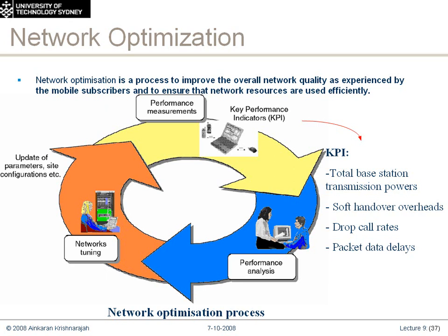So if you can think about moving the angle of the antenna backwards, so to speak, then the radio signal sort of goes up in the air a little bit more, and then hence covers the black spot a little bit better. But at the same time, what it does is it puts a down tilt on the other side where it's actually increased, right? So you've got a problem there. So you need to do 5 or 6 different sites at the same time just to work out one black spot. You can't isolate that one particular problem. That's what usually tends to happen.